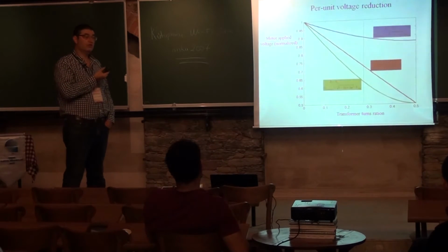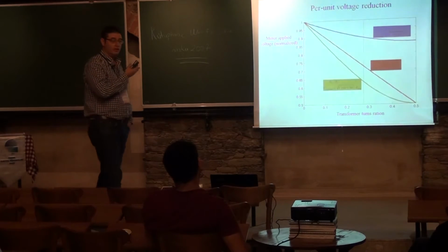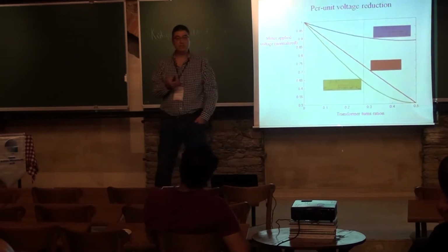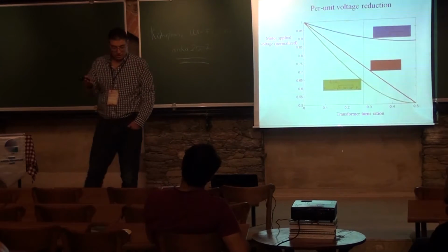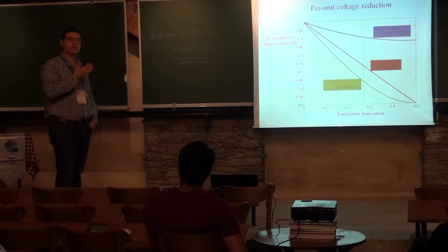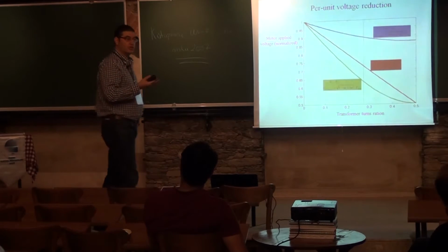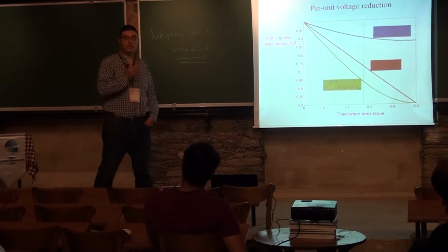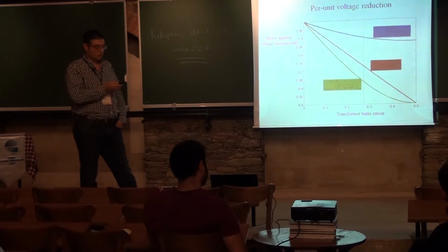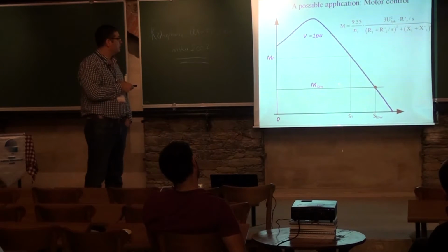What we can do is reduce the voltage towards the machine. Of course, there are many more advanced ways to do this, but these ways are more expensive. They generate harmonics, you need high frequency switching, filtering and so on. This method is purely sinusoidal. You don't have any broken waveforms. Everything is sinusoidal. So this is the idea. That's the machine.